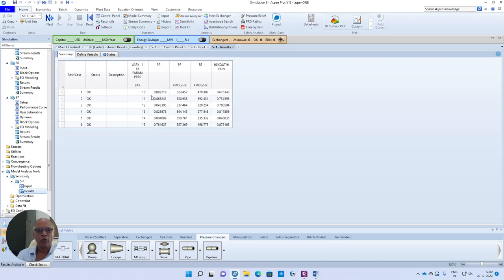So what is happening as you keep on increasing the pressure? What is happening to the purity? It is decreasing. But what is the advantage? You are able to recover more, the recovery of hexene in the product stream is improving. As you keep on increasing the pressure, the recycle flow rate is decreasing, and the product flow also is increasing.